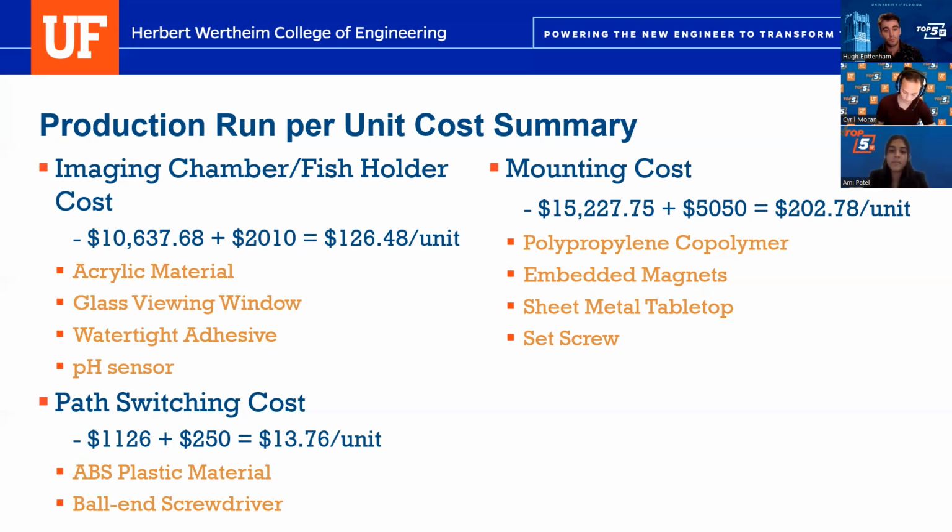trying to complete. A single kinematic mirror mount from Thorlabs costs $115.27. Our mounting system provides 6 mirror mounts as well as the tabletop for only $200.78. This justifies our team's decision to pursue a different route and redesign the mounting system. Additionally, 3D printing was chosen as a manufacturing method over injection molding because for 100 units, 3D printing these mounts is cheaper than the upfront cost for injection molding. However, for a larger scale production, injection molding could be used as a manufacturing method.